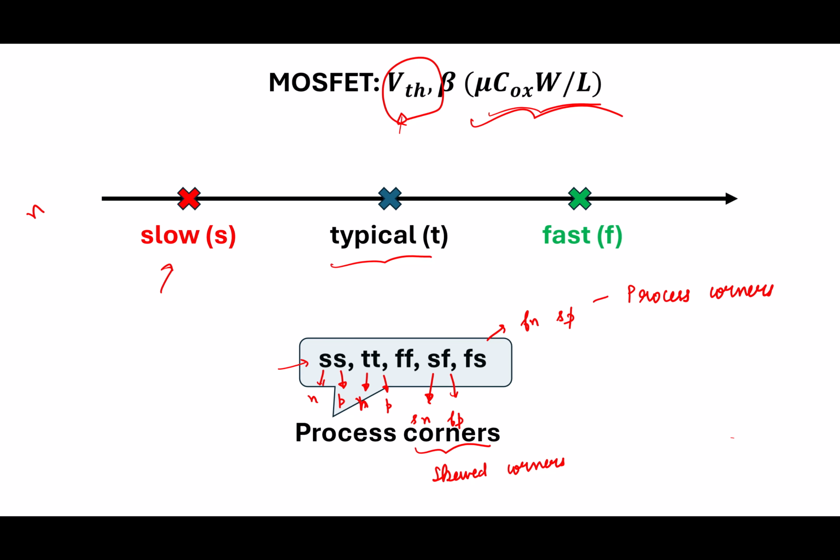In addition to the variations in process and mismatch, process variations and random mismatch, you also have variations in supply voltage because you assume that you are powering with 1 volt, but maybe your battery is discharging, so supply voltage will change slightly. And not just that, you have temperature also varying. You can't say that your circuit will work only in January when the temperature is very low in Kanpur. When it comes to March, it might work, and in July, peak summer, it doesn't work. That's not a practical thing. So even temperature will change.